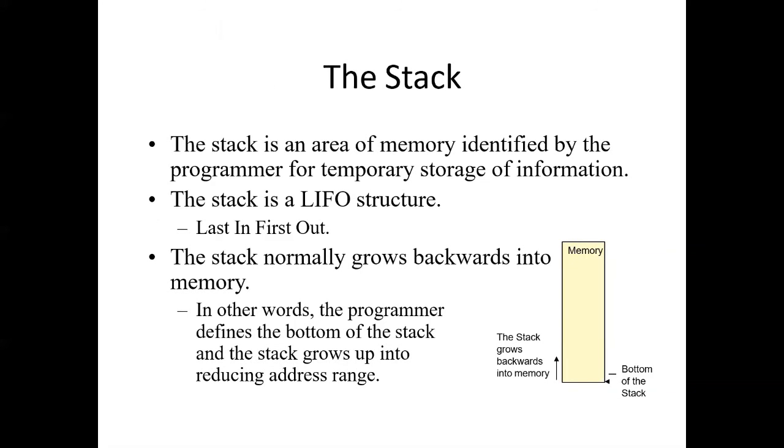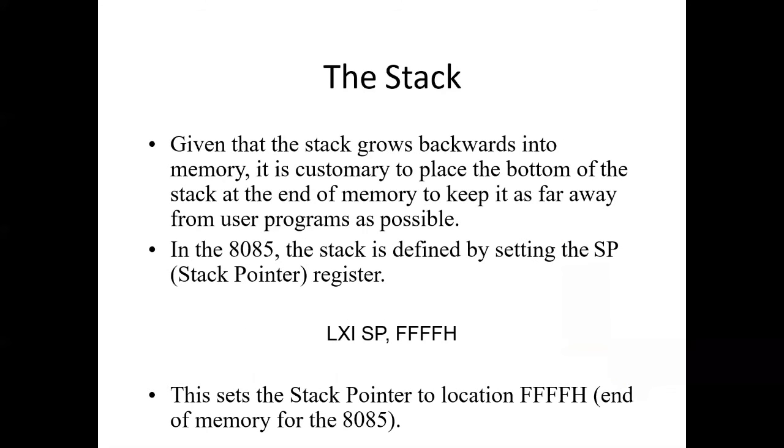So this is the stack area. Stack is an area of memory identified by the programmer for temporary storage of information. The stack is a LIFO structure, last in, first out. The stack normally grows backwards into memory. In other words, the programmer defines the bottom of the stack and the stack grows up into reducing address range.